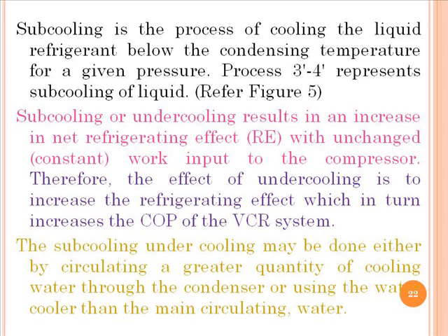The subcooling or undercooling results in an increase in refrigerating effect without any change in compression work. So definitely when you go for undercooling, the COP of the refrigeration system will increase, because RE will increase without affecting the compression work.